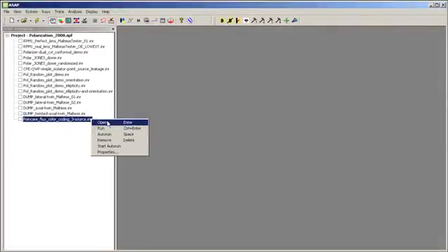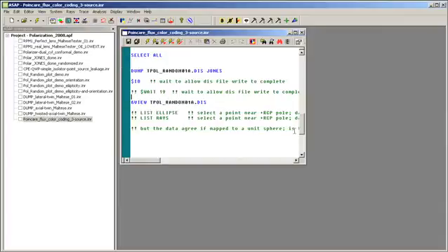So now let's take a look at one final and truly wonderful polarization visualization tool. In the script that you see, I've dumped in Jones format the ray set in my system, and I would like to view it. So I just open it in the 3D viewer like any distribution in ASAP, but now the viewer understands that polarization in Jones format can be turned into a Poincare sphere.